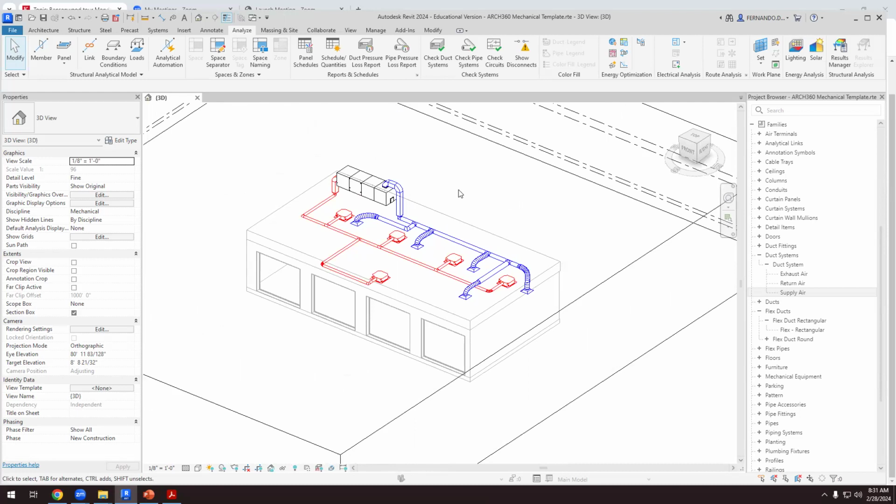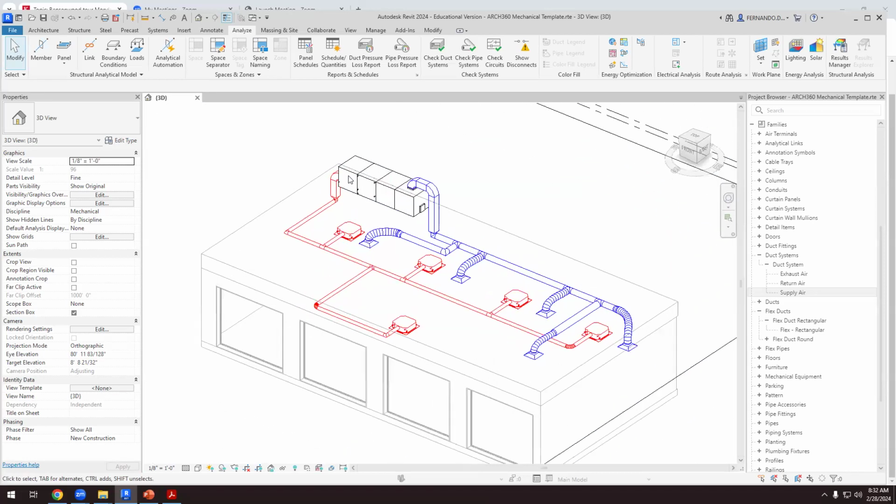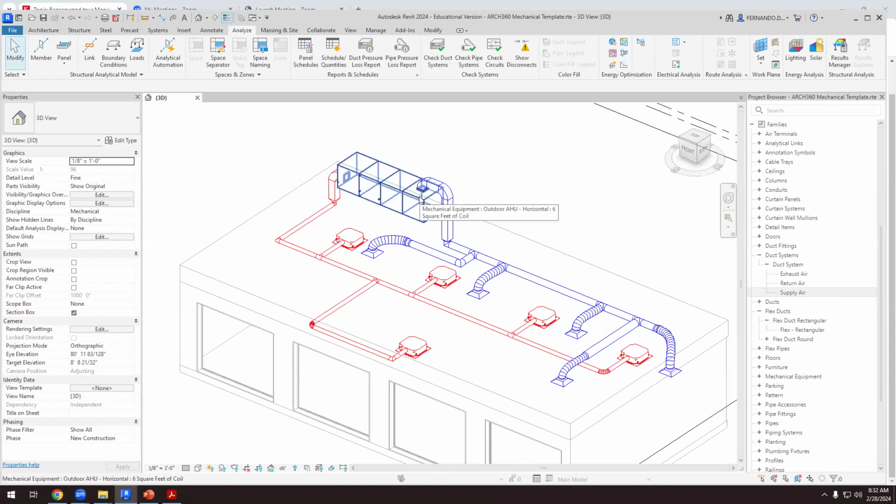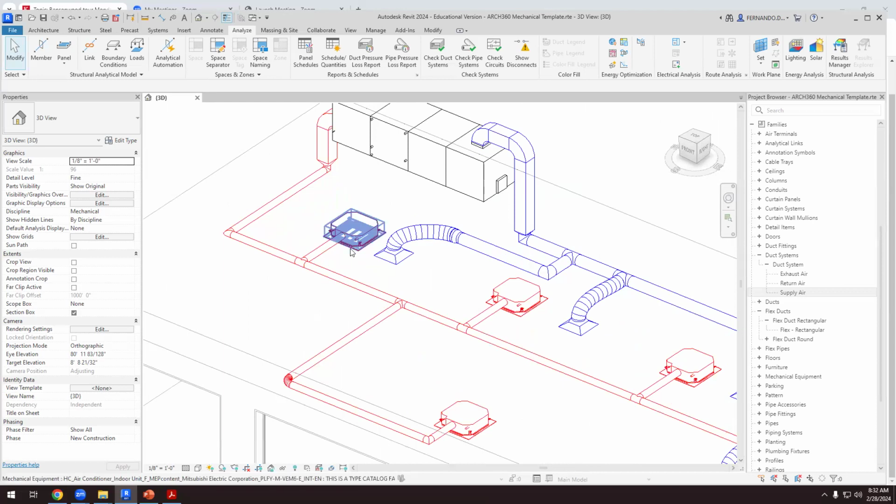We talked about ventilation, and this is ventilation. The ventilation is the air supply that is controlled. We supply air at the conditions that we want. It's fresh air. It has the right relative humidity. It doesn't have particles because here we have filters, and we can get rid of all the outdoor particles that we might find and are dangerous for our health. So the air that we are supplying is healthy air, and then we have to heat up or cool down.